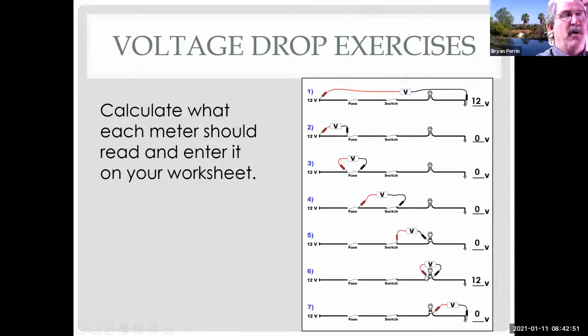But if my bulb only had 10, maybe I'm using 2 volts on the ground because I have a bad ground connection or a bad connection in a wire or a worn wire. Remember, I have to use all my 12 volts in my series circuit. If I have more than one load, don't I have to divide the voltage? So even though he's supposed to get all 12 volts, if someone else has resistance, they're going to steal some of his voltage.